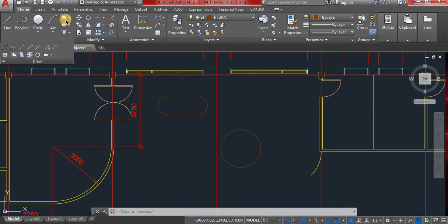But just for your information, the rectangle and polygon commands are also considered polylines because when you draw it, it gives you one solid object, just like this one. It doesn't separate the sides of the polygon or rectangle. So let's go ahead, get back to the spline and click in here to pin this panel. I'll go ahead and choose the spline CV, control vertices, because I don't have exact points. I will just estimate them and do it randomly just to show you how it works.